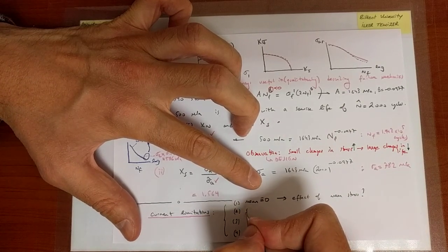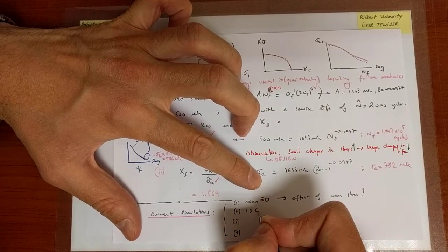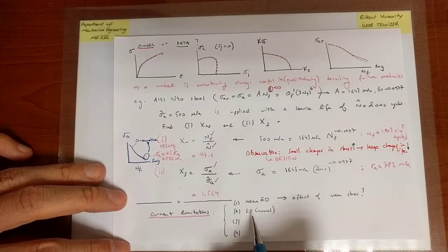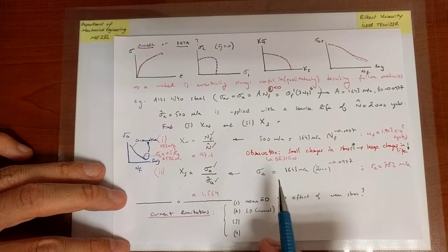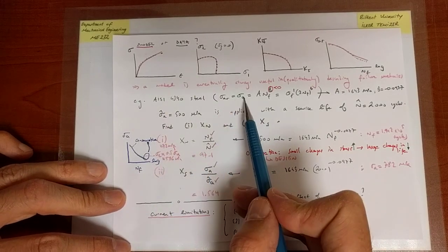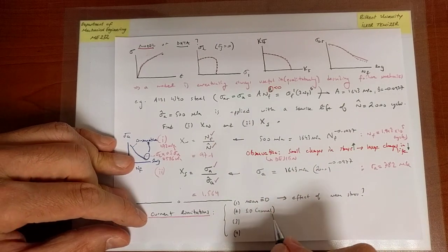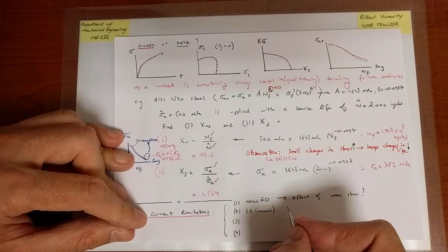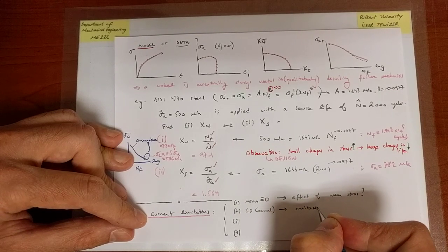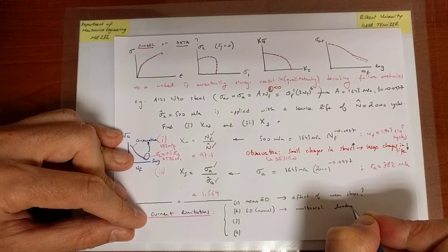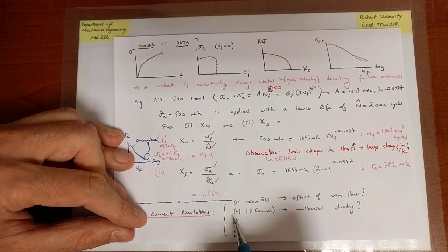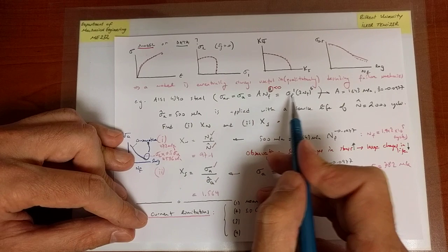Then what follows is the discussion on the nature of loading. The experiments and the analysis so far are only based on a normal stress value; there's only one stress component. So in other words, we're looking at a 1D scenario, but in reality you might have multiple stresses. You can have multi-axial loading, where you have multiple normal stresses and multiple shear stresses, with or without mean. So that's the second thing we have to generalize this relation for.